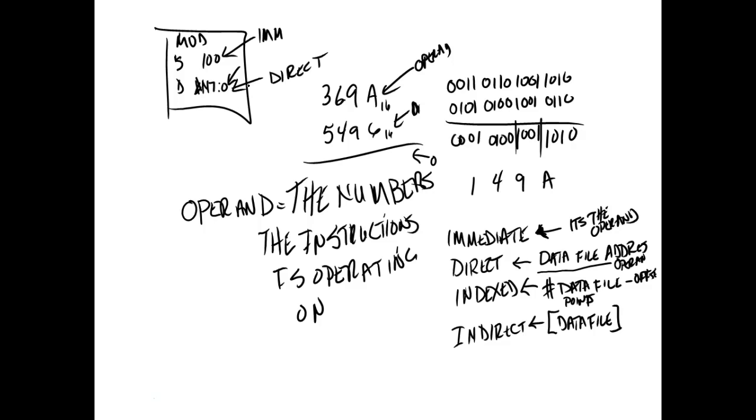This is used most often for going through tables. Index addressing also is very powerful for going through tables because what the processor can do is automatically increment that index register and automatically go through words without us telling it. So we use those on our bit shift lefts and our bit shift rights. We use these on our first in, first out, our stack instructions.